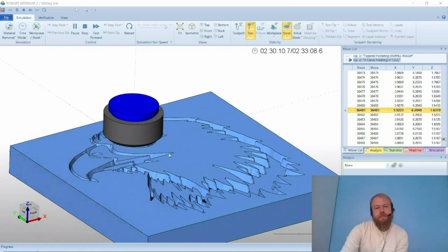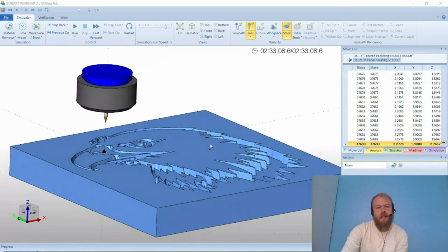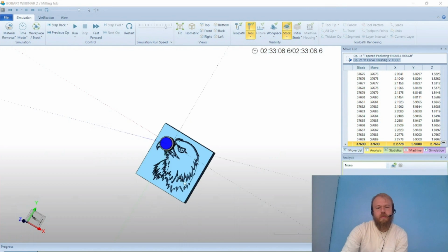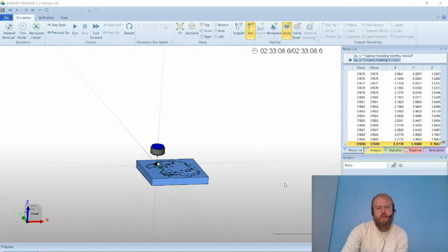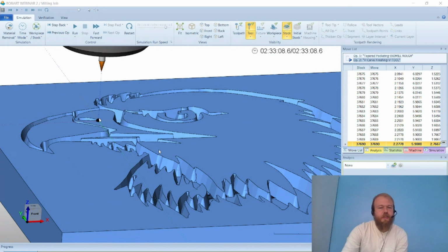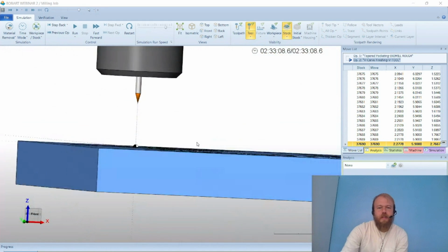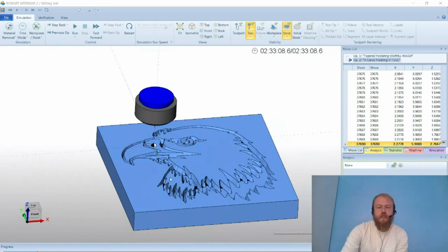So with this one, you can see if we're looking at it from an angle and zooming in. There we go. If I zoom in, we can see everything's flat. We're just using a flat end mill, pocketing down, and then using a V tool to create tapered walls. But on top here, it's all flat. We're going to get into having curved surfaces, so it'd be more like a relief than just the V carving here next with this image.